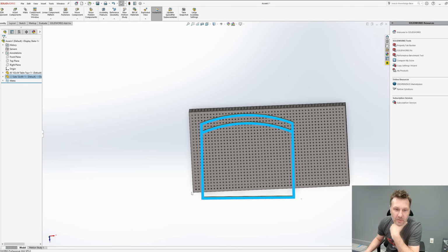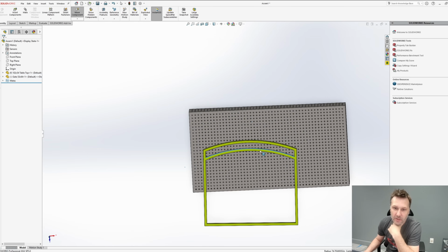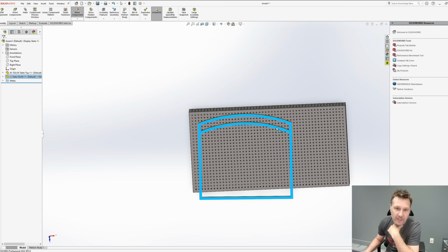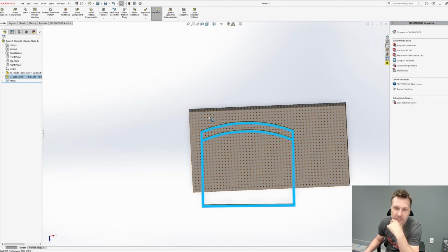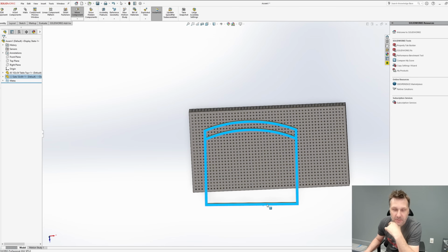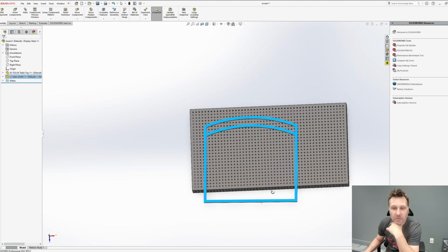Anytime you're fabricating, you're going to be working around the perimeter because this is where you're going to be standing. So positioning parts close to the edge is very convenient. If you're doing a lot of welding here in the center of the table, you're bending over a lot, so try to avoid positioning parts in the middle of the table if you can. Knowing that I've fabbed stuff like this before, we want to leave a good 8 to 10 inches around the perimeter for blocks, fixtures, and clamps.